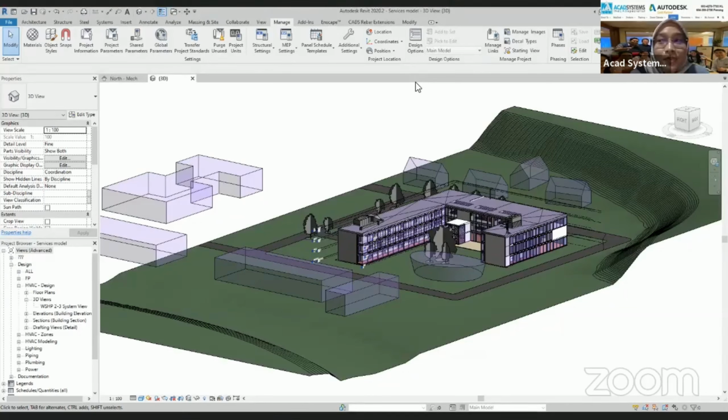Usually, most of the time, Revit is quite simple. We can just move those models using the base point or the survey point, but we don't want to do that repeatedly, right? So that's why we have this by shared coordinate, so that it will save your time later.